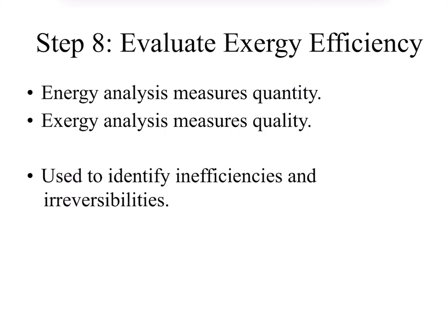Step 8: perform exergy analysis. While energy analysis tells us how much energy exists, exergy analysis tells us how useful that energy is. This helps engineers locate inefficiencies.